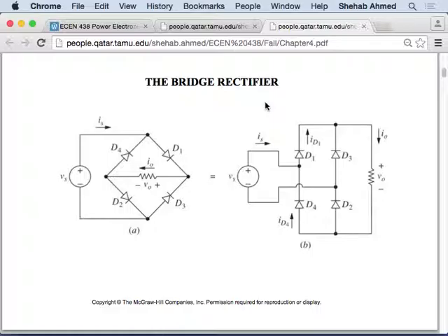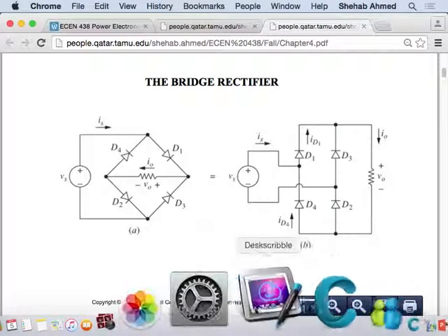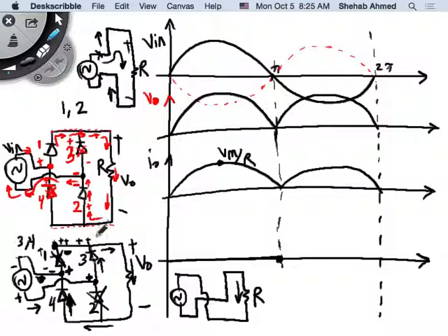So if you put the positive terminal here and negative here, let's look at our drawings. It's seeing what? The negative voltage here and the positive voltage. This is the positive terminal of the supply, placed across the diode here. So this is VD, this is my diode, and I'm seeing the supply voltage put across it this way. This is the polarity of VD.